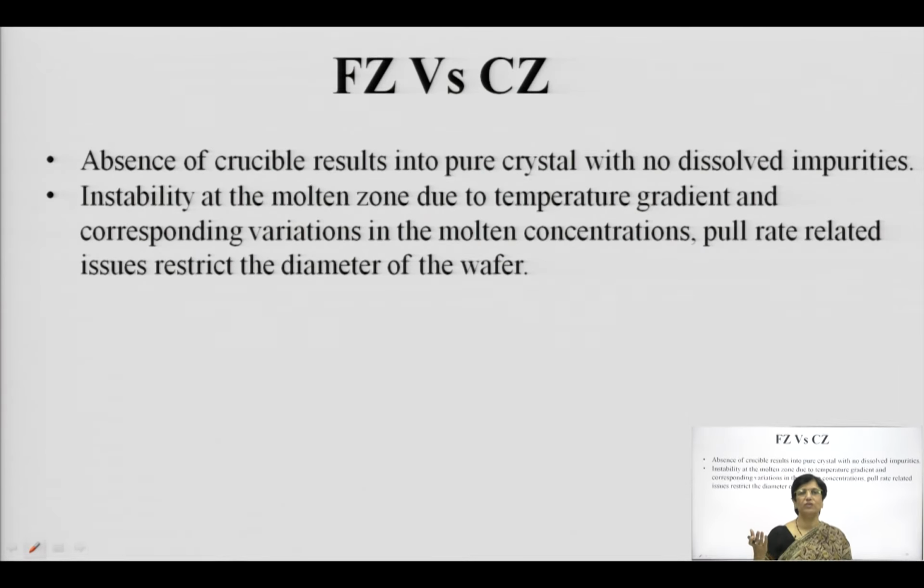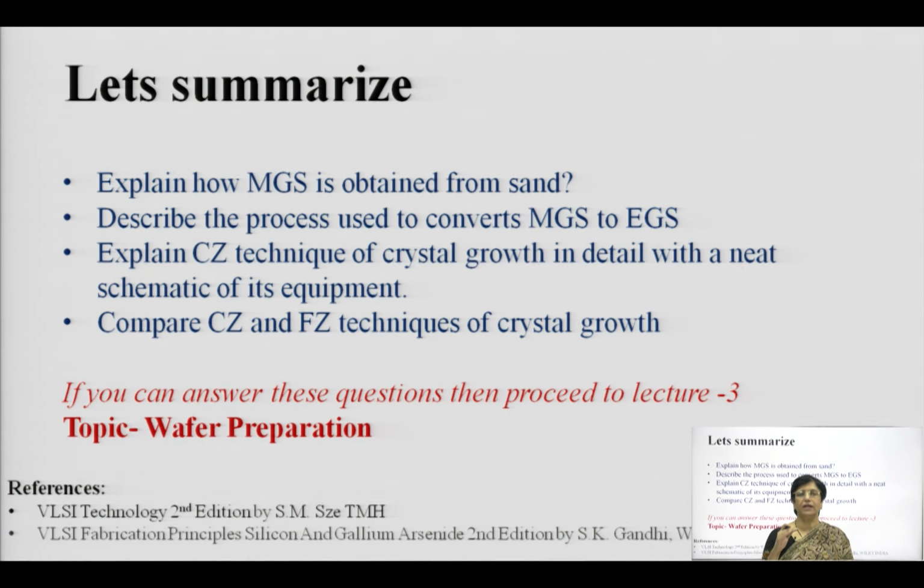So, rather than monocrystalline, you will have deformities or dislocations, or point impurities and surface impurities getting incorporated in the growth process. So you have to be very careful with the pull rate and the contact established between the seed crystal and the localized molten silicon area.